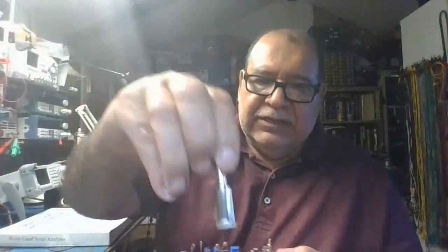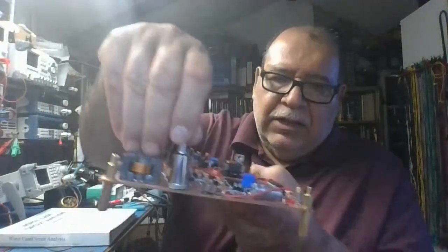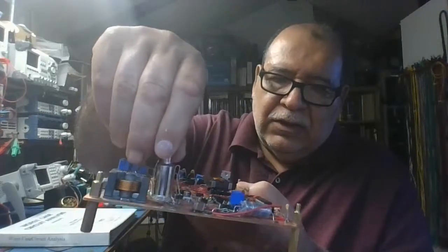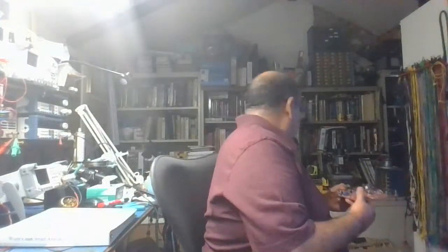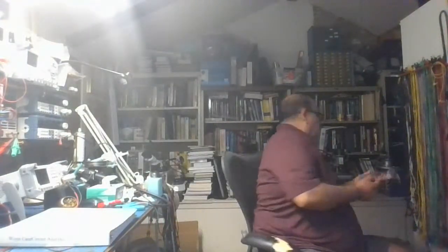So you get yourself a little drill press. You cannot use a hand drill. If you try to use a hand drill, you're going to scratch it up. These are diamond tips, and what it does is it makes a little round cut. Let me see if I can show you. Okay, this here's a good example.